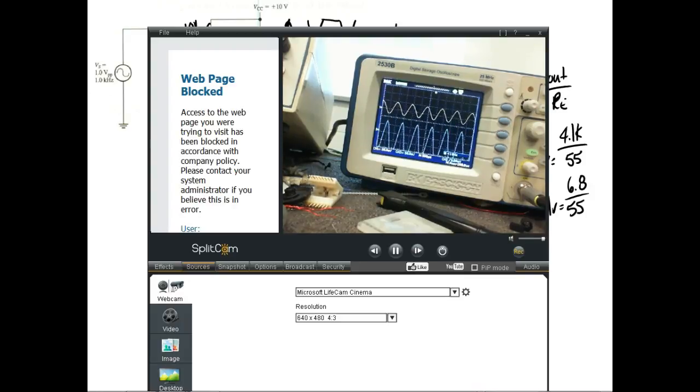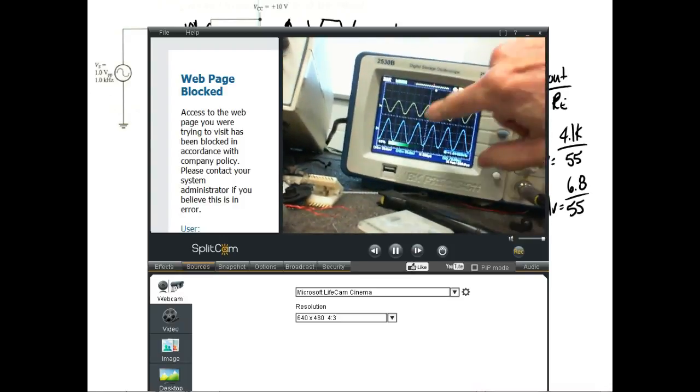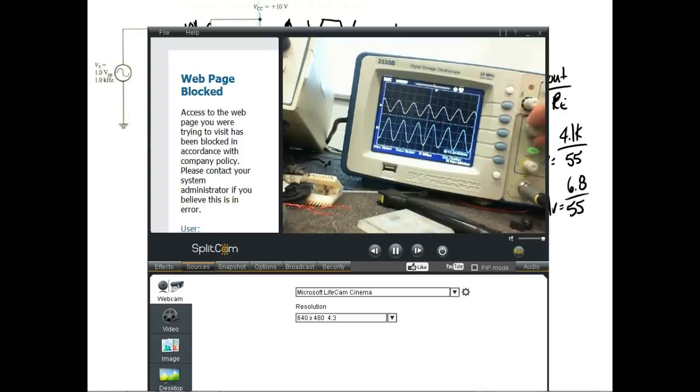Make sure I get to the right place. Okay. Here's the load in there. So right now we're getting a gain. We're putting in, this is 50 millivolts coming in. We don't need to maintain the 10 millivolts anymore. And I'm not bypassed. Sorry guys. I've lost my bypass. Okay, there we go. And we need to lower the input. You can see my output starting to, there we go.